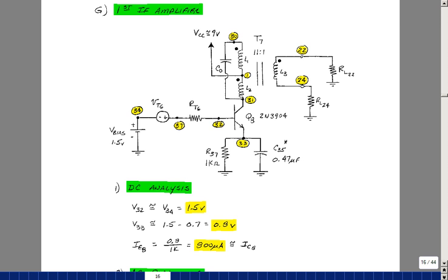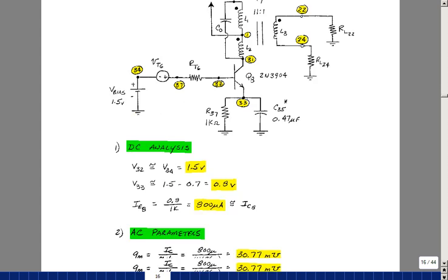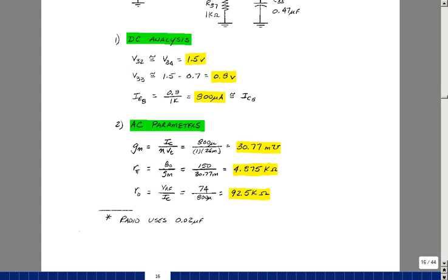Here too again, at resonance, we're going to have this top half of the circuit literally disconnected from the bottom because of this short circuit here. We're going to represent this capacitor as two capacitors, then we'll have a parallel resonant circuit. Whatever voltage is here is then stepped down and shown up over here by the square root of the inductor ratio. Let's calculate those things and see how things come out this time, but we'll include RO.